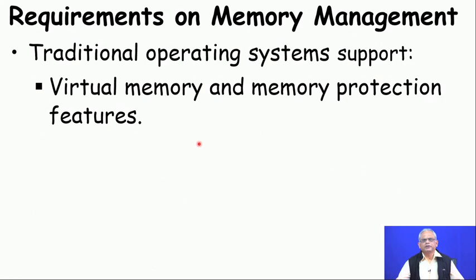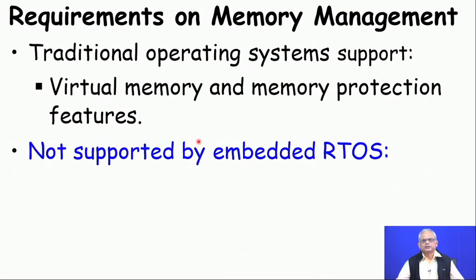There are requirements on memory management. For example, in the virtual memory system and in the memory protection features, we need improvement. Of course, in very small embedded real time operating systems, where the task size is small, only very few tasks, and the overhead of the operating system needs to be very small, the footprint or the size of the operating system needs to be small, then the virtual memory is not supported.